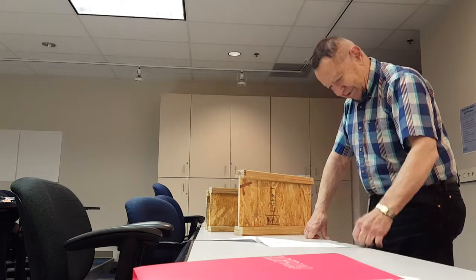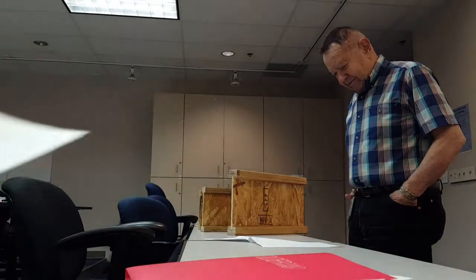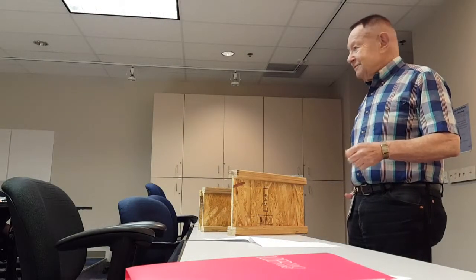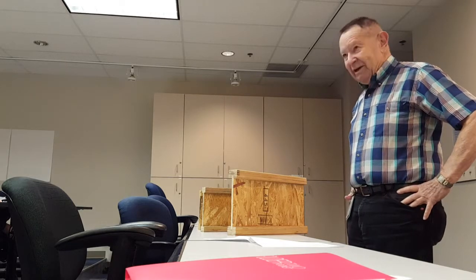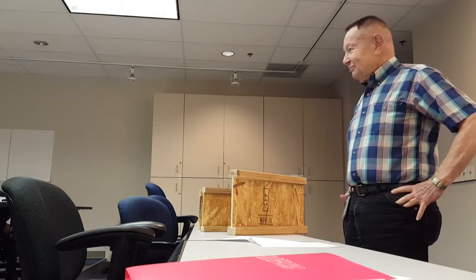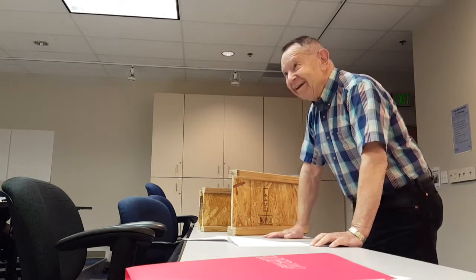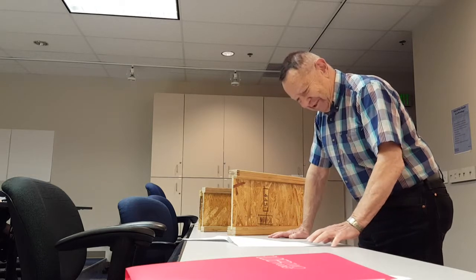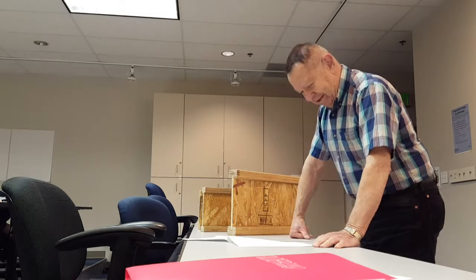237.95 times the density. And then if you compare that with 2x10 dimension lumber, which is actually, they say 2x10, but what you get is 1.5 inches by 9.5. This is the world we live in. Nothing's what it says, right? And so anyway, you see that would be a single rectangle.